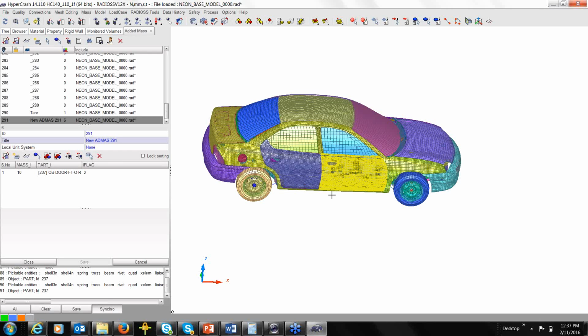But if you were just doing a frame, which might only have 20,000 elements, if the element size is smaller, that's okay because you're also having fewer elements, right? Yeah. Let me emphasize a little bit about the smaller size. When we talk about FEA, finite element, it's really a basic approach. It's an approximation. We approximate so that the physics meets reality. In order for you to have an exact or a pretty good approximation, you need to be closer to the physics, meaning I need to capture all the element size.